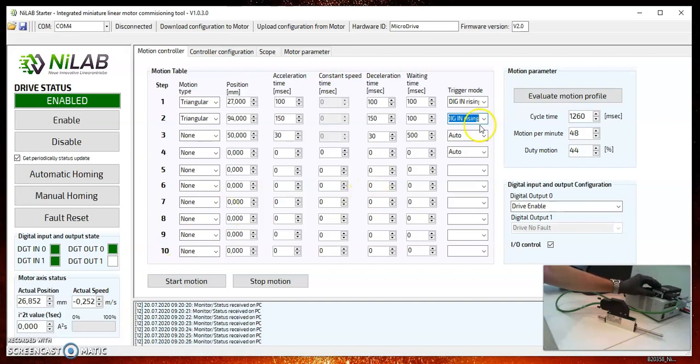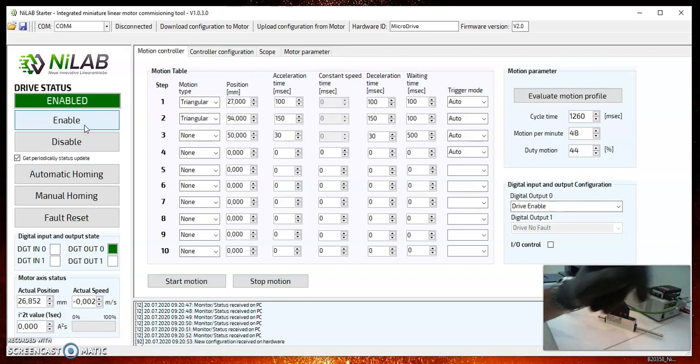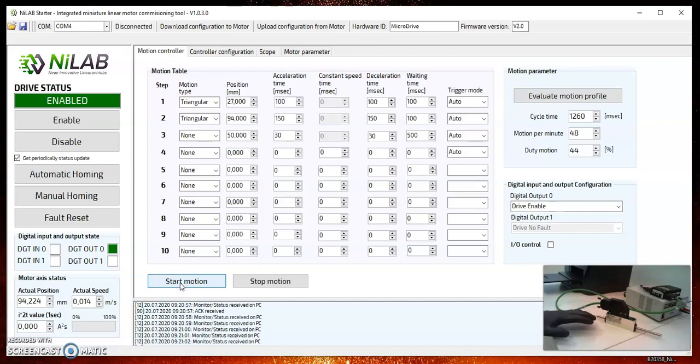So let's go again on the PC control. So switch off the digital input 1, switch off the digital input 0, then disable the I/O control and move to auto on the table and download the configuration. Now again our control is on the PC and we can start the trial motion using these 2 buttons, start motion, and then we have again the automatic sequences.